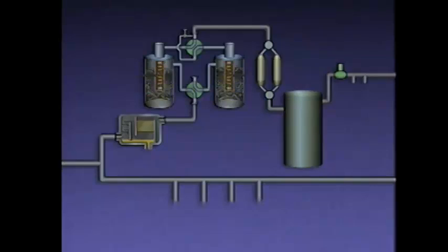Dry filtered air that is suitable for use in a control system is typically stored in a receiver until it is needed. Then it is sent to a pressure-reducing valve. The valve's function is to reduce the 120 psi air to 50 psi for use in pneumatic instruments and devices